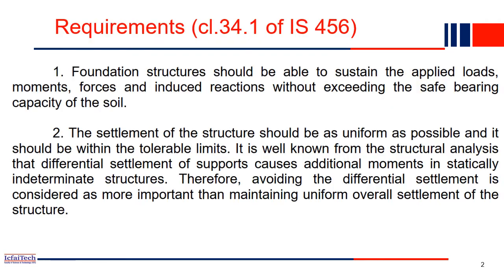So let's get started. Before we start our foundation design, let's see what requirements we have. The requirements of foundation you will get in clause number 34.1 of IS 456. So what are these requirements? The foundation structure should be able to sustain the applied load, moment, forces, and induced reactions without exceeding the safe bearing capacity of the soil.